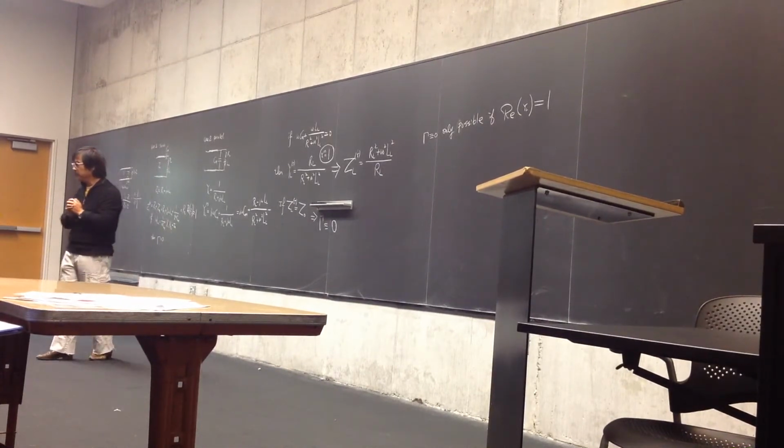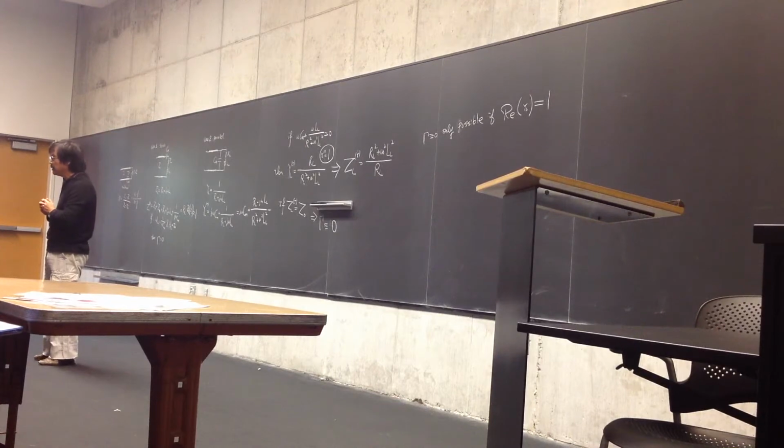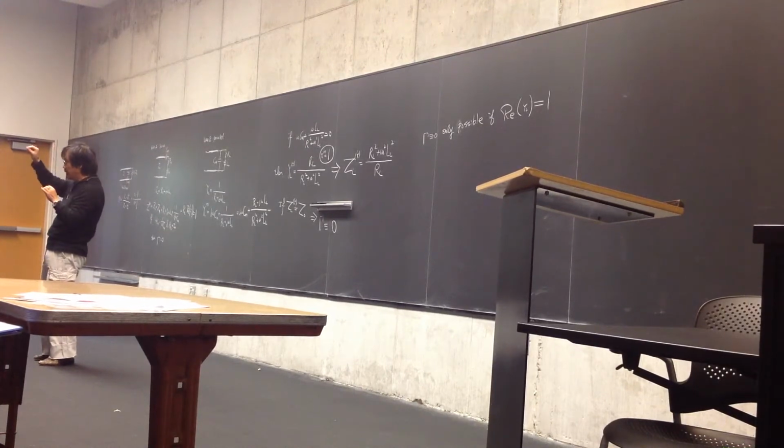So the way that we're doing the Smith chart, we find the matching capacitance or inductance load, and then based on that, we find where that lines up on the Smith chart, and that's how we find where the real part of the admittance is 1. You see, you have this load impedance already. So you have a load. So you can draw a point on the Smith chart.